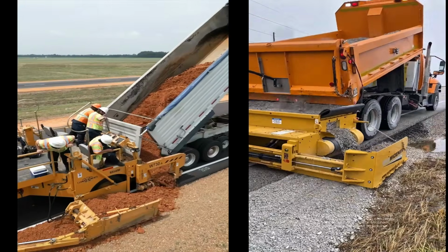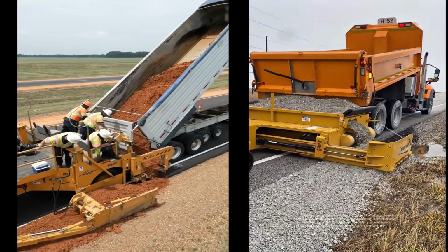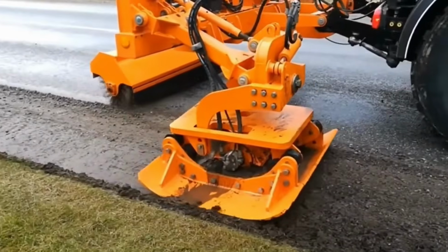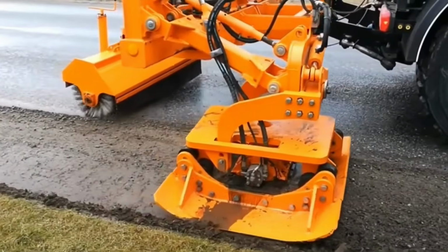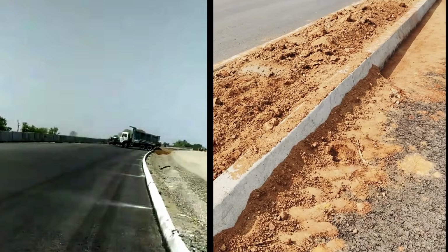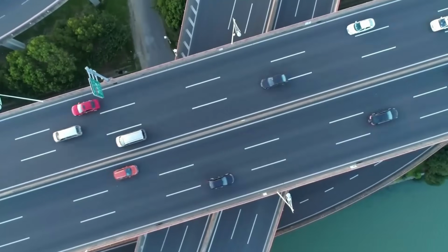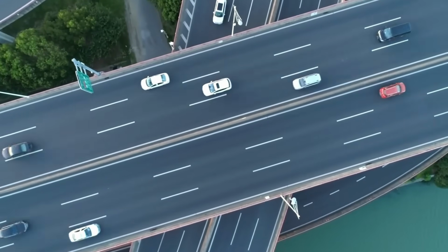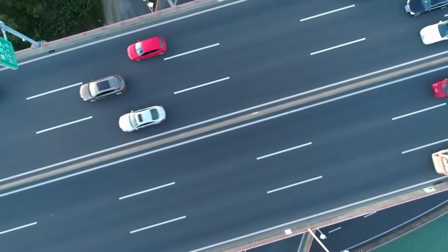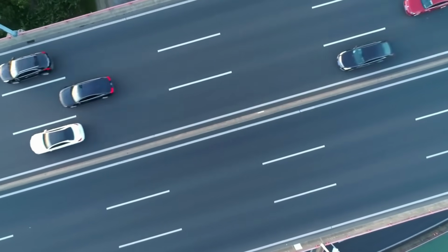Typically, a single layer of road base of about 10 centimeters thickness, along with a thin layer of asphaltic screed, is used as the topping for shoulders to seal the road base. Finally, miscellaneous works shall be completed. If this episode changed how you see highways, you are already thinking like a highway engineer. This is the common procedure used in road construction projects.